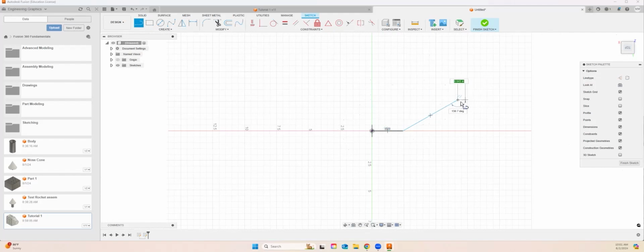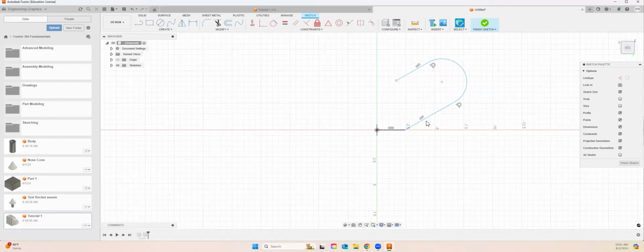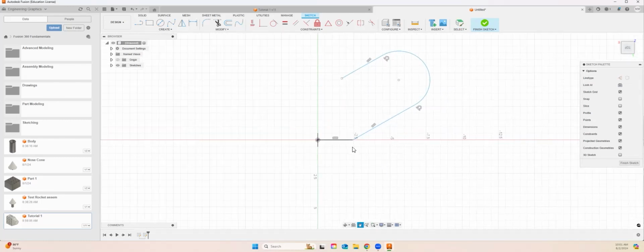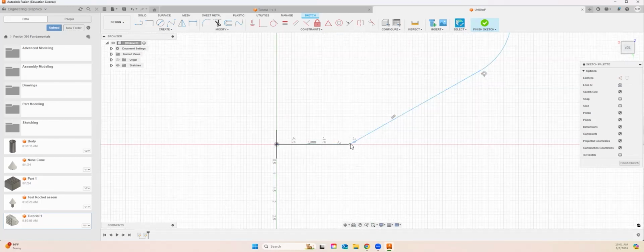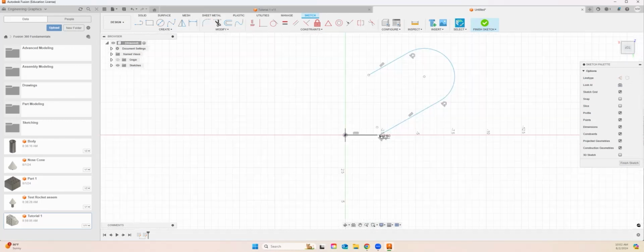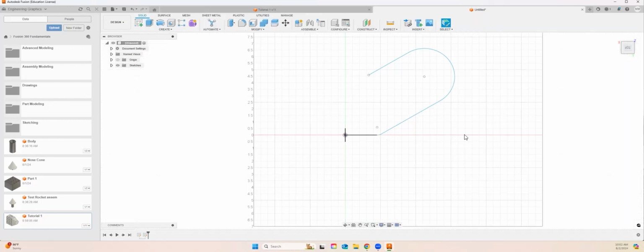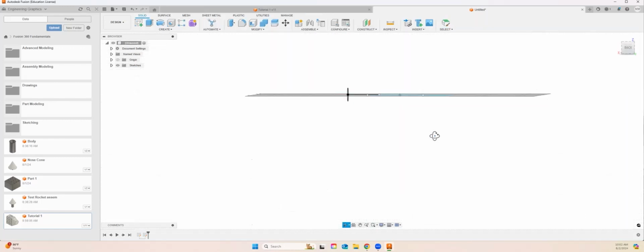And if I click and drag before I press it, it becomes something like that. And then something like this. So you can do any shape that you want, as long as they're rounded and smooth. Hopefully this one will work. We have this edge that's kind of pretty sharp. So I will do a fillet, clicking these two areas. 0.6. Yeah, sounds about good. And you can see a fillet, so it's around there. So hopefully this will work. All right. And if not, we can change the fillet.